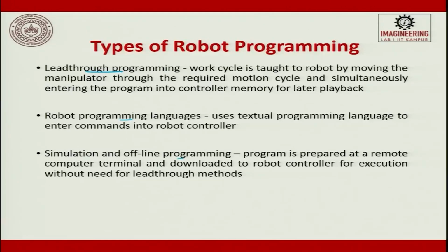Lead through programming: a work cycle is taught to a robot by moving the manipulator through the required motion cycle and simultaneously entering the program into the controller memory for later playback. So, it is just like holding a blind man and walking him through, using a teach pendant to do that. So, lead through programming is that.